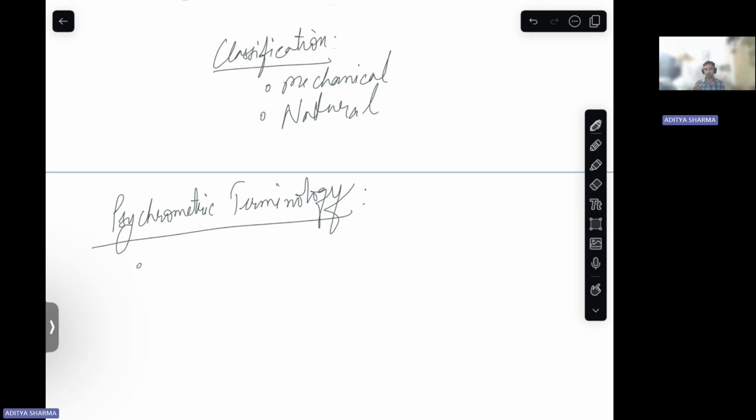Okay. So by saturation, I mean the vapor content in the air. So there is a limit to which air can hold vapors. When this limit is reached, we call the air saturated. It no longer can take vapors. Okay. So when air enters, it is unsaturated, right? So evaporation in the tower takes place, and this becomes saturated.